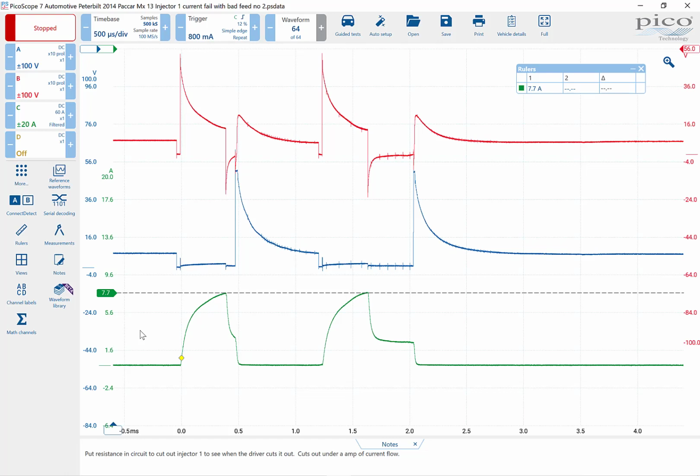Also, another thing to keep in mind on the ground side of the injectors, on these solenoid style injectors, if you look here, you've got your inductive kick, okay? So normally if you have a good inductive kick on your ground, and it's where it needs to be, around 50 volts or so like I showed you, then what that means is the overall internal health of the injector itself is in good shape, because as soon as you open the ground circuit, it creates a back voltage, and that's due to the magnetic field that's been generated inside that coil. Okay, so then the energy from the coil reverses polarity. Instead of staying at ground, it spikes positive. Okay, and that's what's going on inside this injector. All right, so that's another good telltale sign to look for good health of the coil itself.